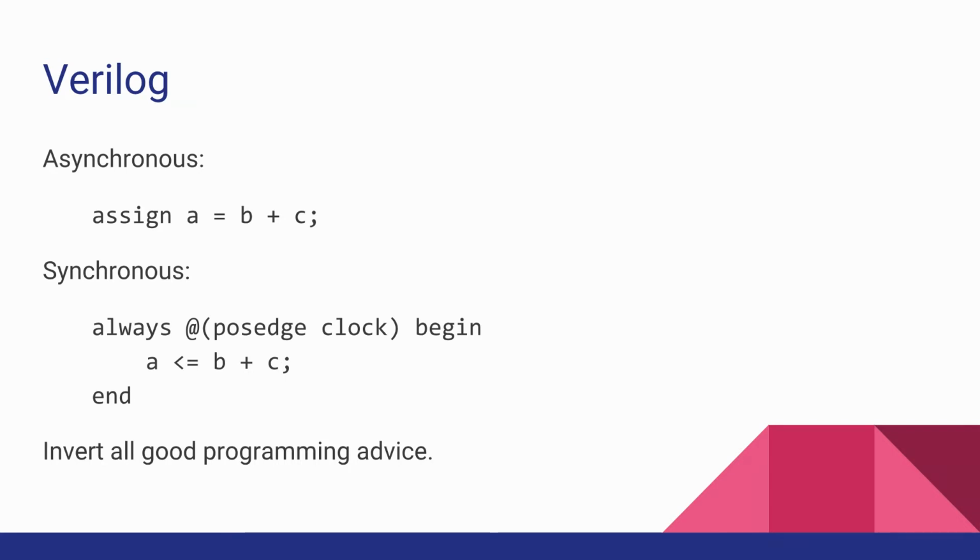And so when you change B and C, that happens between clocks, and all this noisy stuff that you get out of the adder goes nowhere. It just gets stuck, and right on the positive edge of the clock, everything gets settled, and you get a nice clean signal into it.